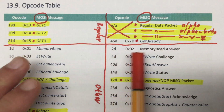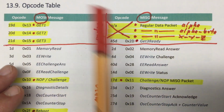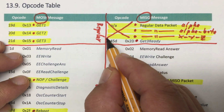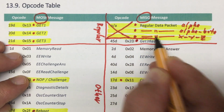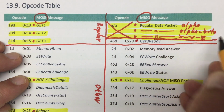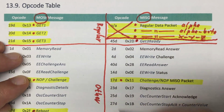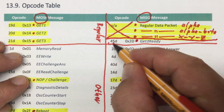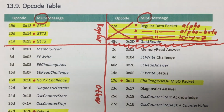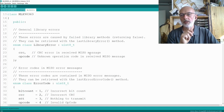It has a marker of 11 for other message and carries the MISO opcode hexadecimal 2D. And of course, we find that message here also in the opcode table, and I just realized I made a mistake here because it has a marker 11 for other message. So it belongs to that block here, and this has to go. Sorry for that.